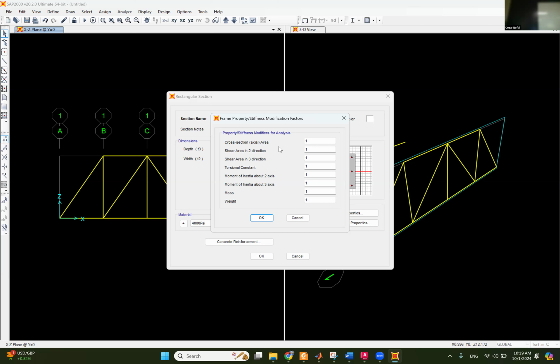That depends on the element and depends on the loads that we're dealing with. But if you have a structure, like let's say the column behind you, and this column is cracked. Yeah. So maybe you look at the width of the crack, maybe you look at the size of the crack, and ask, based on the crack, how much of this area is not contributing to the total stiffness of the element. Okay. All right, so these are the parameters. We are gonna get deep into the modifiers, but I'm not gonna change the modifiers right now.